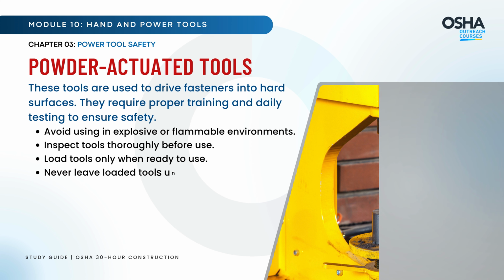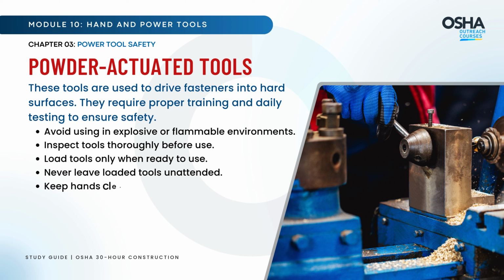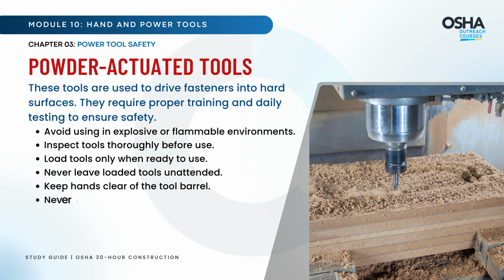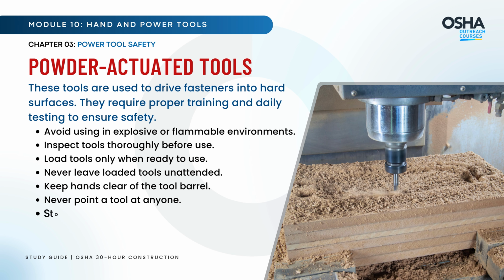Never leave loaded tools unattended. Keep hands clear of the tool barrel. Never point a tool at anyone. Store unloaded tools in a locked box.